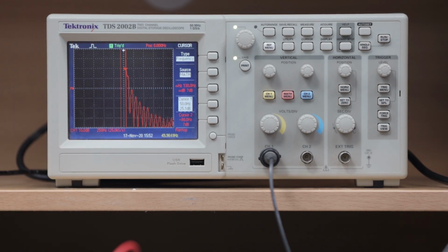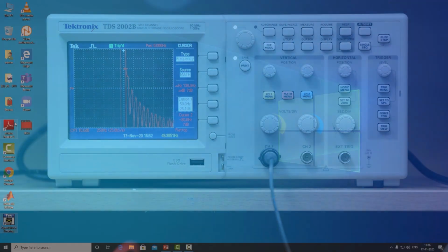This value you have to calculate as the V fundamental RMS, and the formula is 20 log V fundamental RMS equal to dB. Now V RMS fundamental is equal to the inverse of 20 log of the dB value. Then you will get the V fundamental RMS at 50 Hz. This FFT analysis you want to capture in the PC.